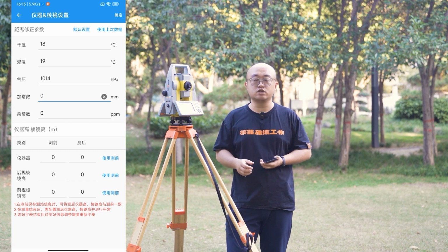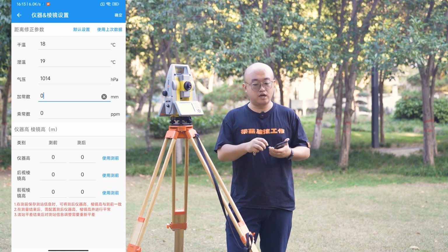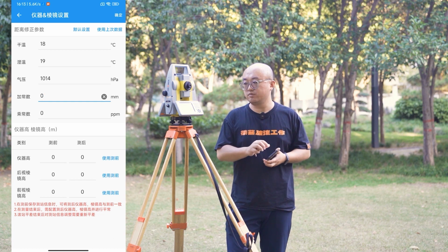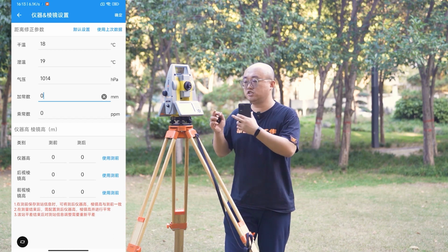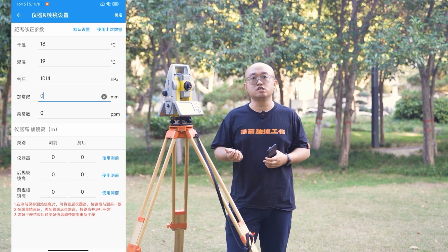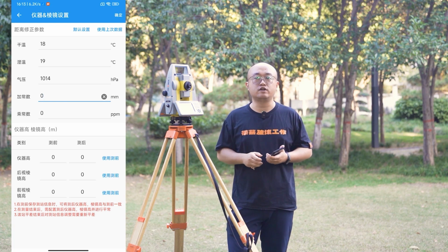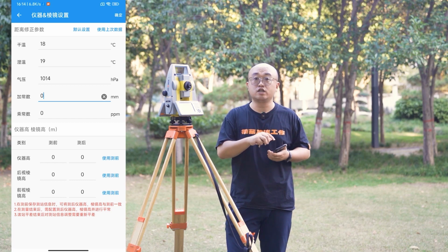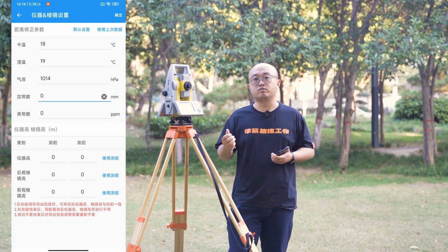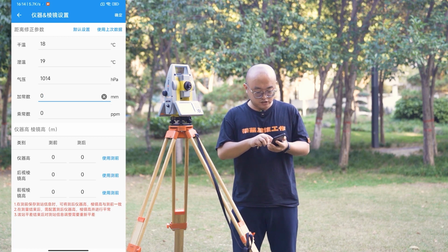If you need to fill it out, you can use a thermometer to measure the actual temperature, pressure, and the actual multiplication constant. Secondly, if you make corrections on the software, there is no need to make corrections on the instrument. If there is an atmospheric correction setting on your instrument, keep it in the default state, which is no correction, because the software and instrument only have one place to correct it. If corrected on the instrument, the software will remain default. If corrected on the software, the instrument will remain default. Do not correct twice. Then, we will record the height of our instrument and the height information of the prism.